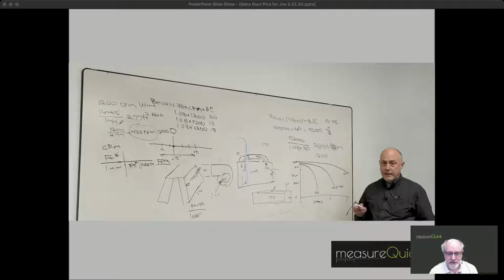As you can briefly see on my screen here, we're talking about the BTU concept, and that actually goes along with doing a great design. Your Manual J, if you do a block load, it's a little more difficult, but when I do a room-by-room load, I can actually determine how many BTUs and how much CFM would be required to make this room meet those loads. Not everybody's doing that. The block load gives me an overall CFM, and then people figure out a way to design what they need for those rooms.